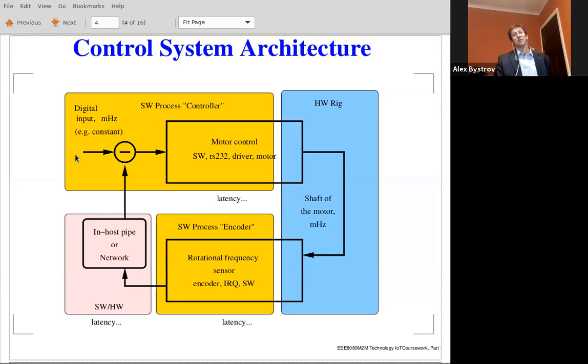What do I mean by sufficient? Sufficient needs to be as long as needed in order to finish the observation of the oscillatory process, right? So it depends upon how well the system is designed. In our case, I think that something like 5 seconds will be more than enough. If the system doesn't settle down on some particular rotational speed within a second or 2 or 3 or 4, it will be a rubbish system.